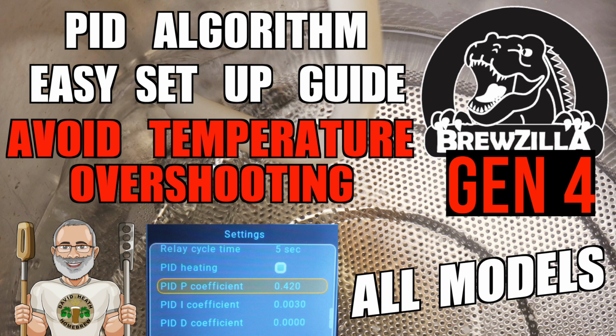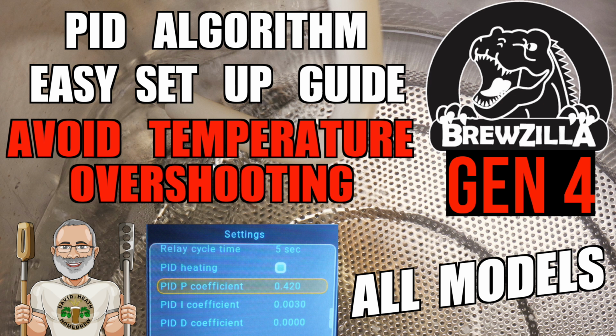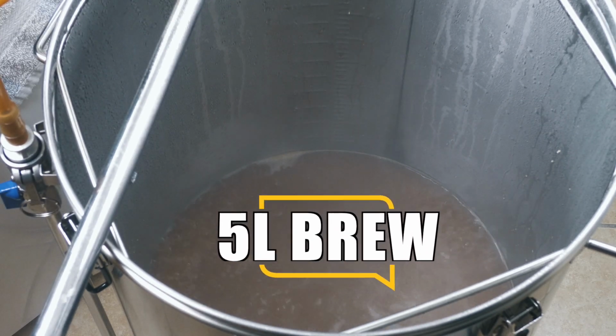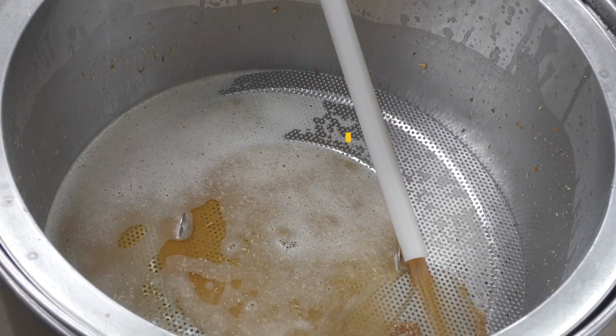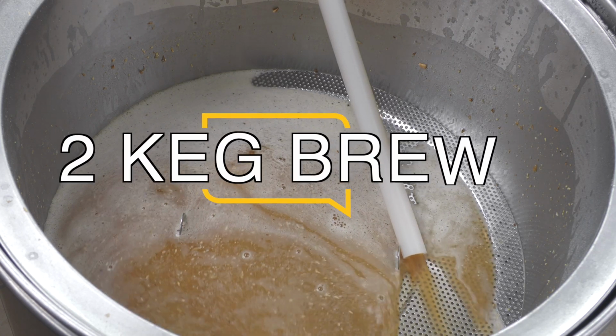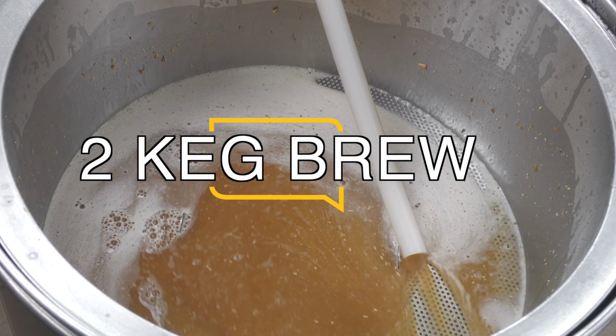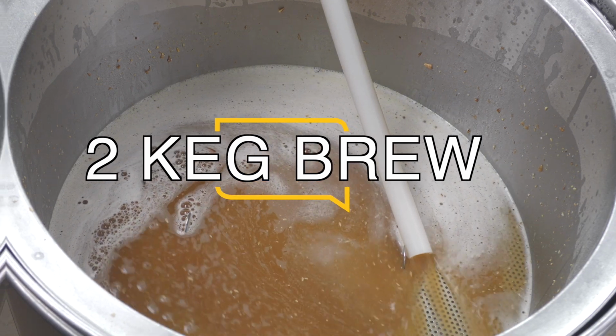Within this video we'll be looking at how to set up your Brewzilla GEN 4 to avoid temperature overshooting, and at the same time explaining everything that you need to know about the wrap system's PID algorithm for brewing. So let's get started. Brewing systems incorporating what is known as PID algorithms is nothing especially new, but with Brewzilla GEN 4 you have a much wider amount of volumes that you can brew within one system than ever seen before in an all-in-one. So for this reason there really is the need to be able to tweak your PID algorithm to accommodate this, and thankfully Kegland have opened this up for the user.